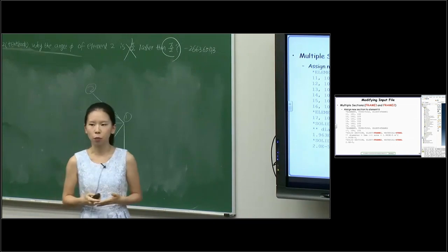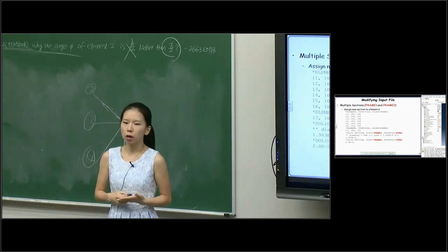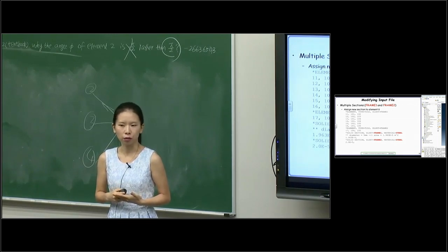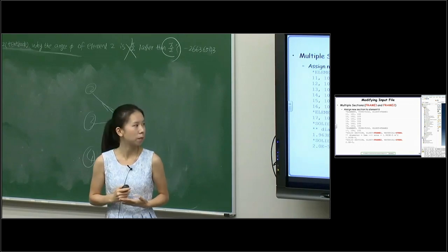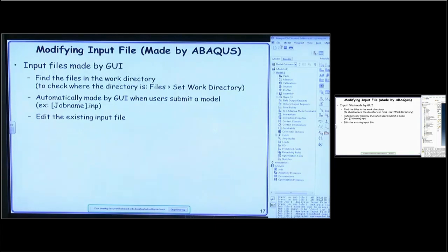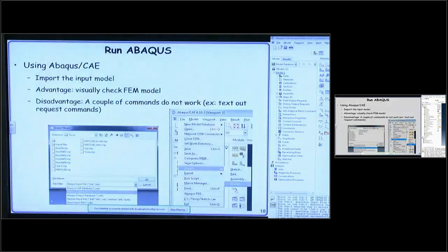So in the end, we can imagine that each member in the whole structure will have almost the same stress, close to allowable stress, but each member probably will have different cross-section area. That is what fully stress design means.